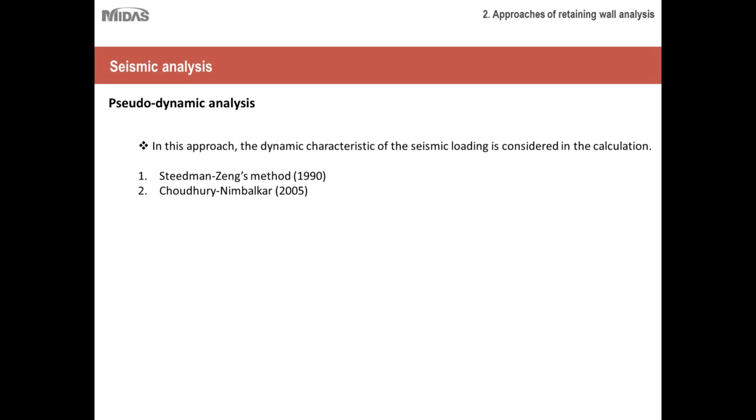Wherever they need seismic analysis, if it's a low seismic zone and they want to do some quick and easy checks, they go for pseudostatic analysis. And if they have to consider dynamic analysis, or if they have access to numerical analysis, then for seismic analysis they mostly go for numerical analysis.